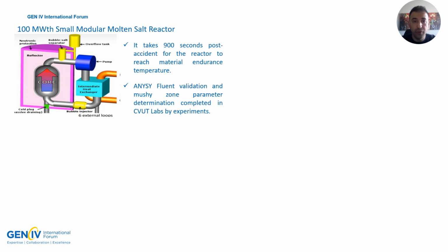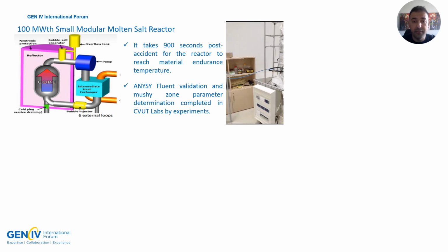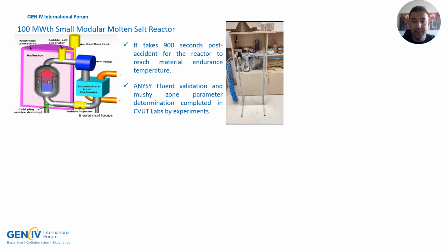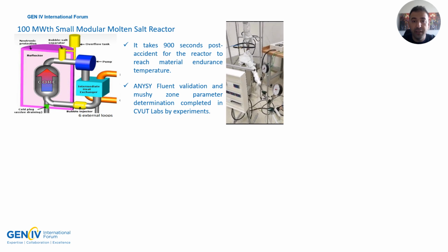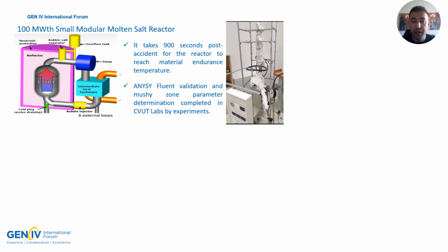So first of all, I did ANSYS Fluent validation and also calculation of the determination of the mushy zone parameter in Czech Technical University laboratories. So we can see here our experimental facility. We are using a freeze plug here and make a lot of measurements, temperature and pressure.